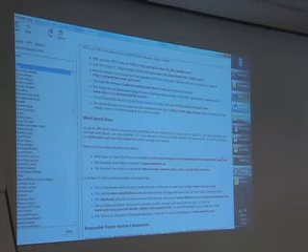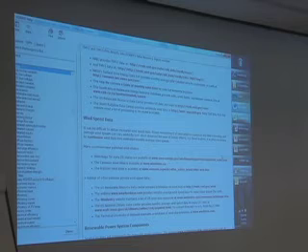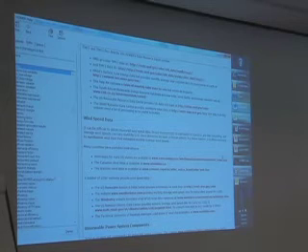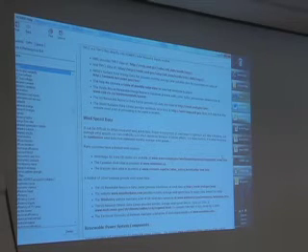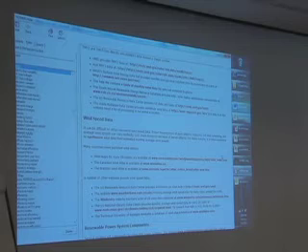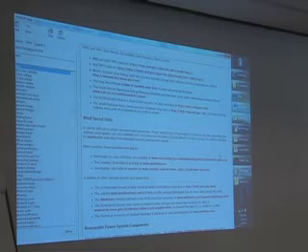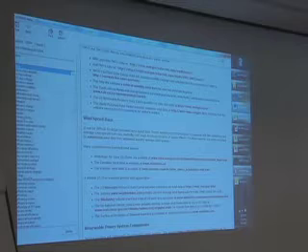It takes a text file with 1 line per data point. So if HOMER sees 8,760 data points, it knows that's an hourly data file. If it sees twice that many data points, then it assumes it's a 30-minute data set. So it tries to calculate what the time step is.